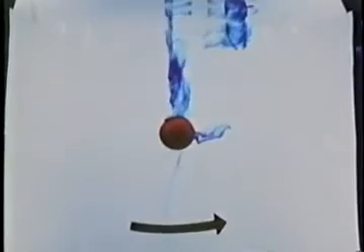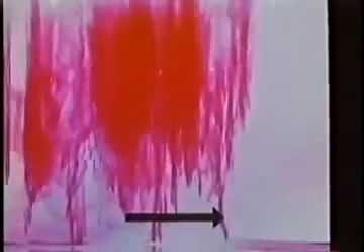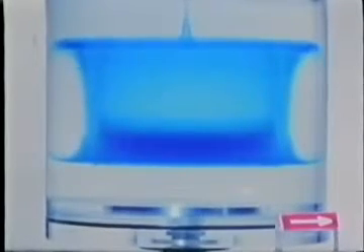In this film, you have seen many of the effects that occur in nearly rigid rotations of homogeneous fluids. When Rossby numbers or frequency ratios are high, we often see rather direct reactions to the Coriolis forces. Or we may have distinct oscillations associated with the rotational stabilizing tendencies. When Rossby numbers are low, the strong vortex tube effects and geostrophic adjustment to the pressure field produce unexpectedly two-dimensional flow fields, low-frequency Rossby wave modes, and reactions to viscous forces that are quite unlike those of non-rotating fluids.